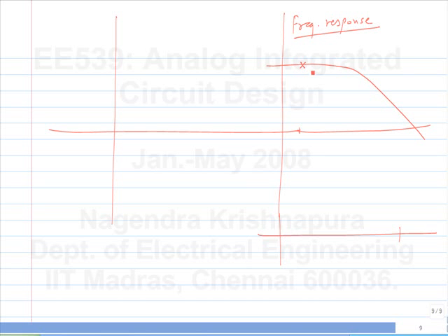So now what happens is, you see that the response is getting attenuated. So what I'll do is, I'll place some complex poles just beyond where it is starting to roll off. Then the system itself likes to ring at that frequency. So if I apply a signal, its natural response will help the forced response also. Okay. Because without this, the tendency was to attenuate the sine wave.